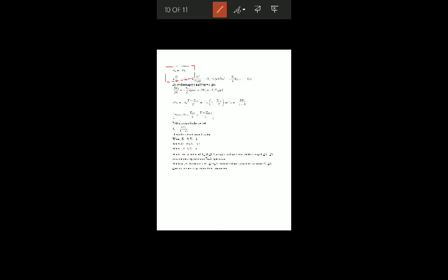Again we represent VL equal to L di by dt equal to minus V naught, and di by dt as delta I by T off. Rearranging the terms, we get delta I equal to V naught by L into T off.